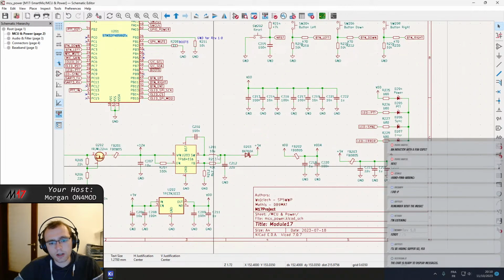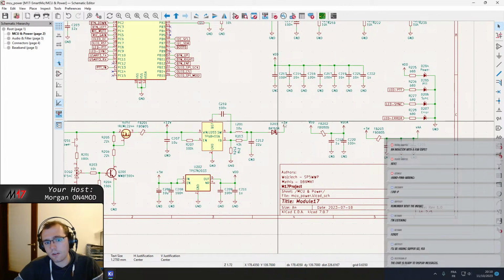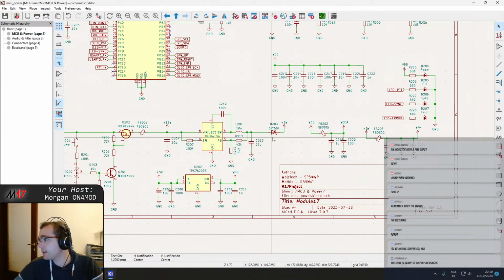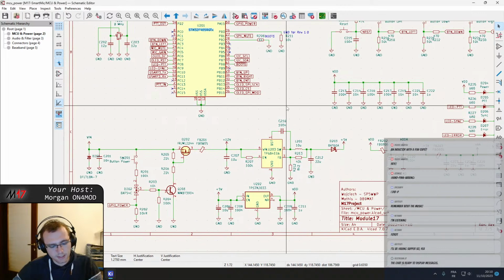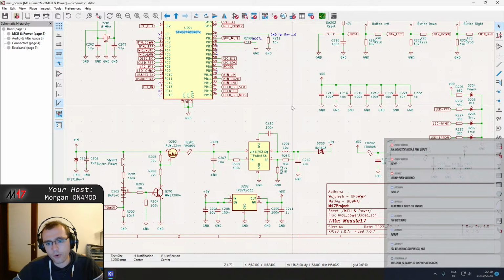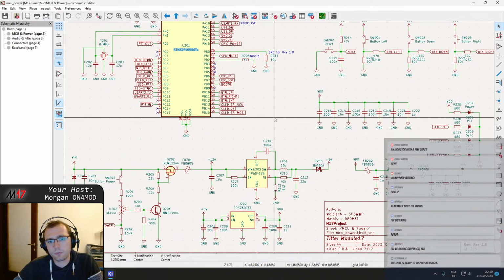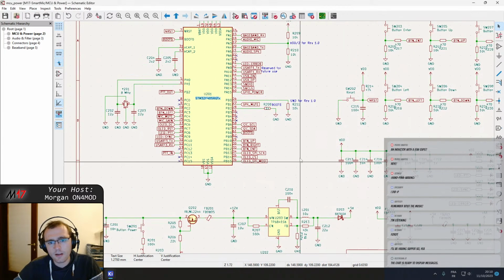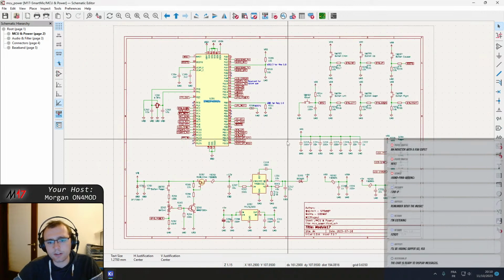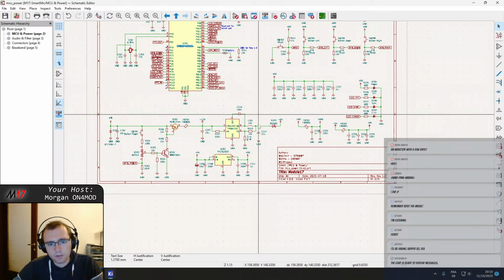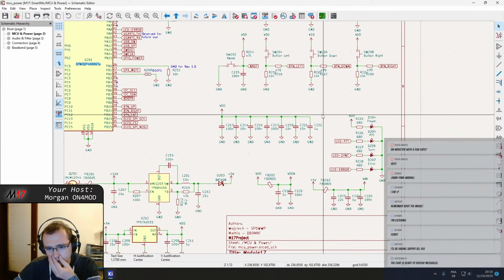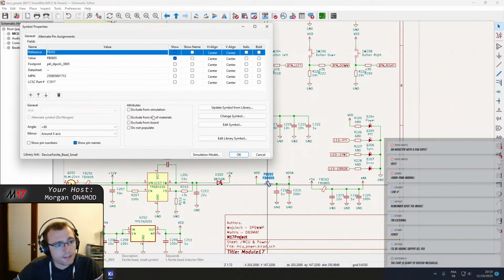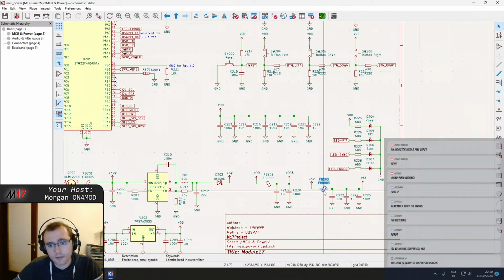But for the analog rails and so on, just like you say, Pierre, it's going to be ferrite with gaps, an LC filter basically. It doesn't get any better than that. Of course, RC filters are not feasible because we can't add a resistor in the path of the power supply. It's not going to work. So, let me think. I guess this one is the same. Yeah, it's always the same ferrite bead.